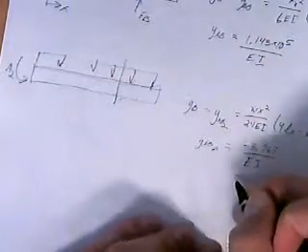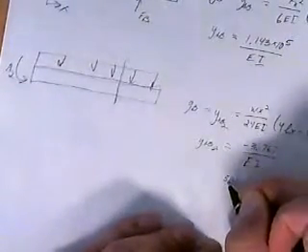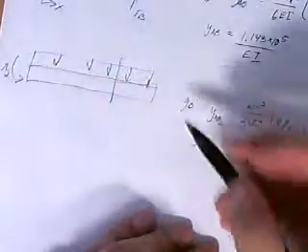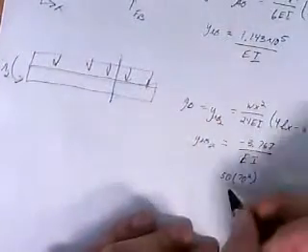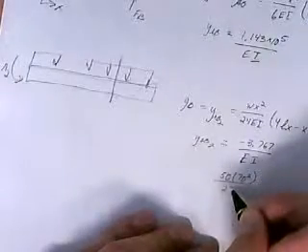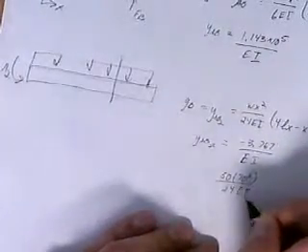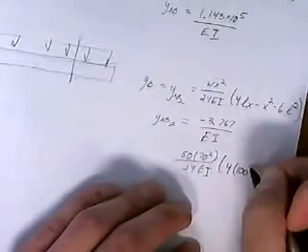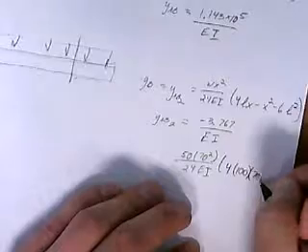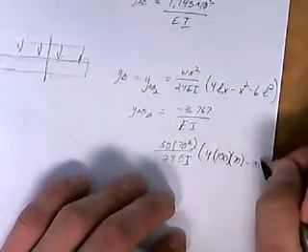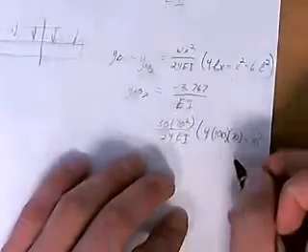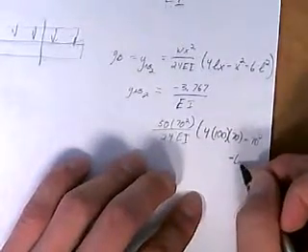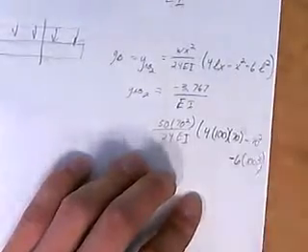So the numbers down here: 50, which is the distributed load, times 70 squared, which is the X up to this line, all over 24 EI, times 4 times 100, which is the total length, times X again, 70, minus 70 squared, X squared, minus 6 times 100 squared.